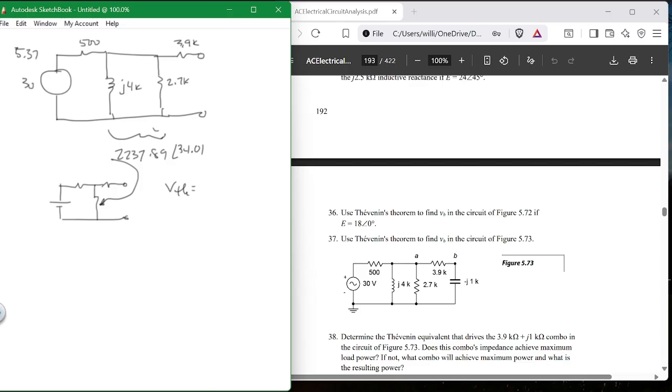And that's why when we get to this point, we stop for a little bit. We all recount how you did Thevenin in resistive circuits, and you say, it's exactly the same way. The only difference is when you do that power thing, you take the complex conjugate, or the complement, or whatever you want to call it. It's the other brother. If it was a plus J, now it's a minus J. That's the only difference. All right? So, what is V Thevenin?